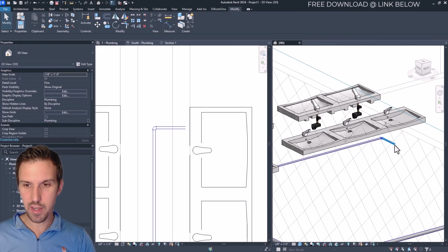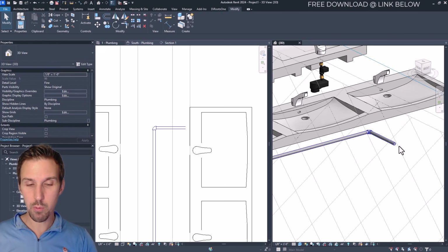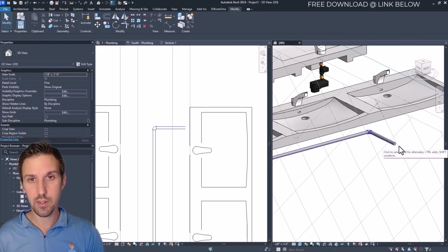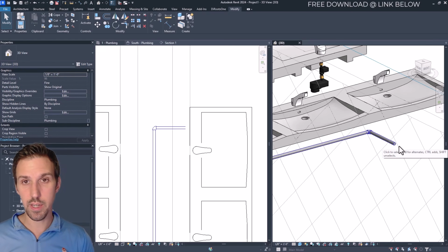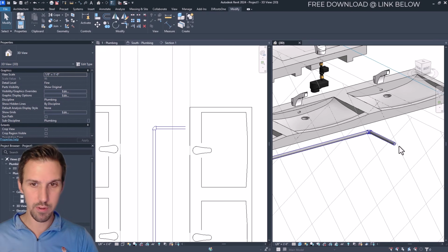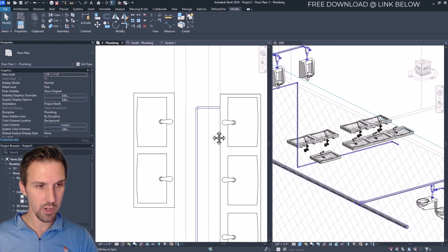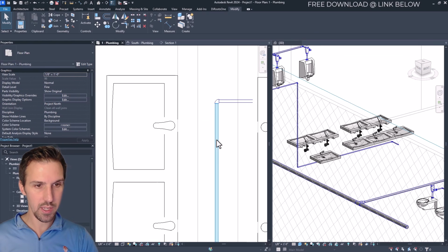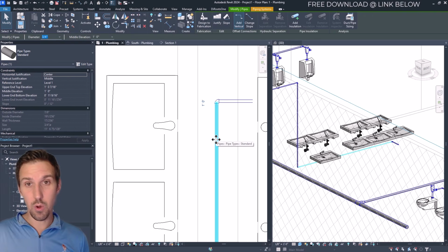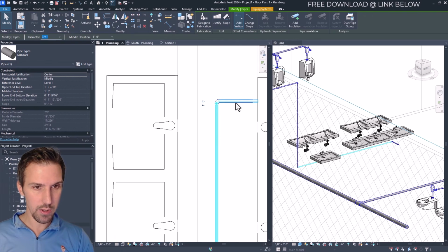So that's going to be the connection point for, maybe we'll also use instant water heaters or tankless water heaters. So maybe like an electric water heater right below the fixture. That's going to supply hot water for all those lavatory faucets. So that'll be the connection point. So let's go ahead and put some more connection points on here. Typically the hot is on the left, the cold is on the right. So we're going to create another one of these.